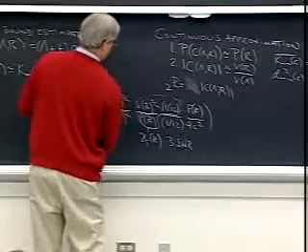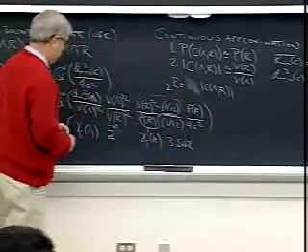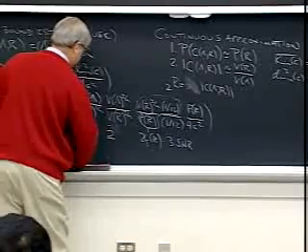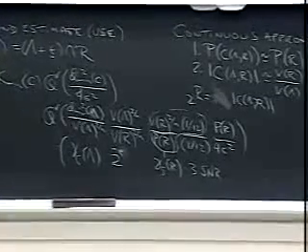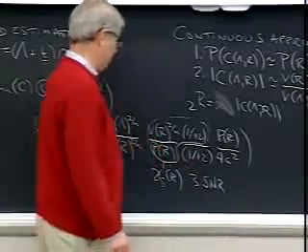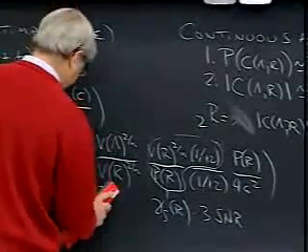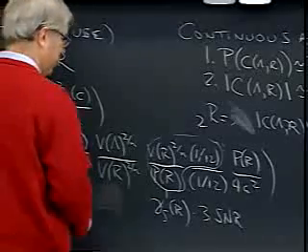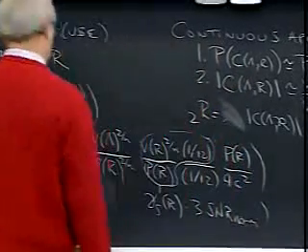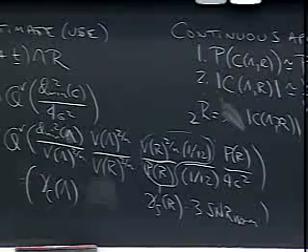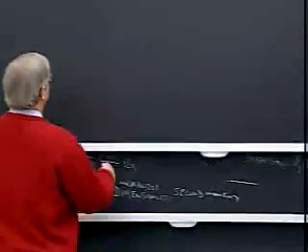Actually, what I want is the spectral efficiency. And the spectral efficiency is the rate per 2 dimensions. So this is just 2 to the minus rho. Okay? So with a little help from my friends, what's SNR over 2 to the rho? It's approximately SNR norm. Certainly true as rho becomes large. It's actually SNR over 2 to the rho minus 1. So this is SNR norm. Okay, so with a little hand waving and a few high SNR approximations, we get that,